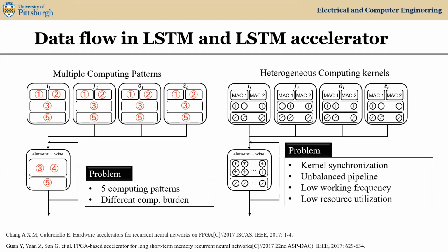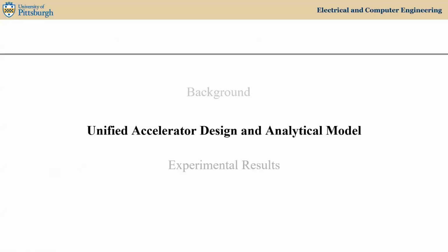Such a design suffers from several problems. 1. Kernel synchronization, for example, synchronizing the MAC kernels. 2. Unbalanced kernel pipeline, such as the pipeline between MAC kernels and the element-wise kernel. 3. Low working frequency due to multiple dedicated kernels. 4. Low device resource utilization due to the unbalanced kernel size. Next, I will introduce my design, the unified LSTM accelerator and its analytical model.